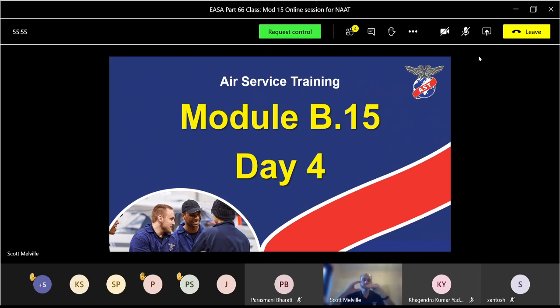The opening will only open proportionally, depending on the pressure in the system, the pressure on the throttle control, and the pressure on the servo controls. I call it a shock absorber for a fuel control system. A nice smooth delivery compared to an open one.